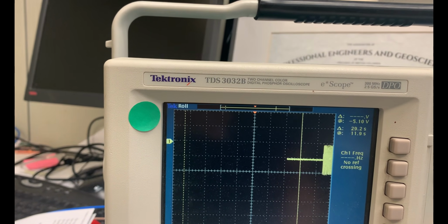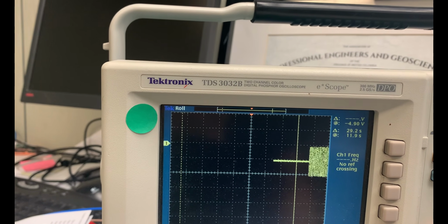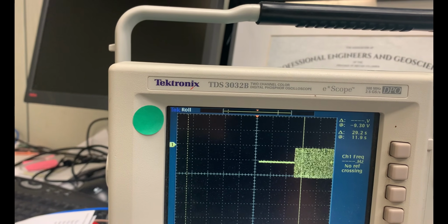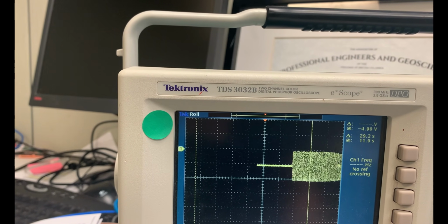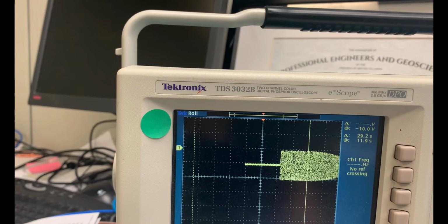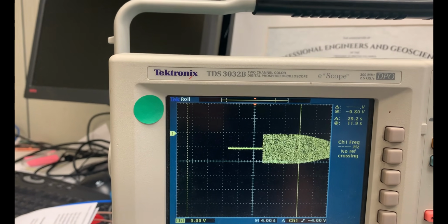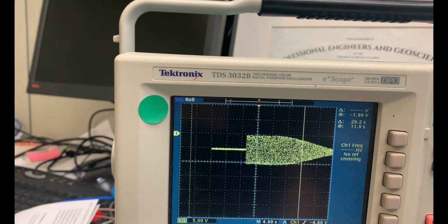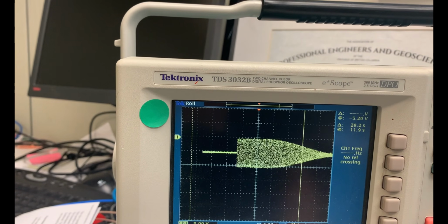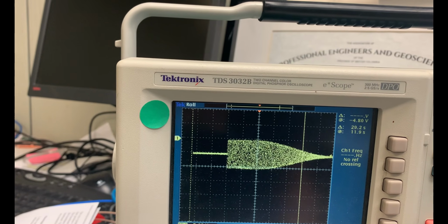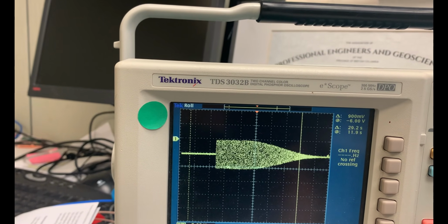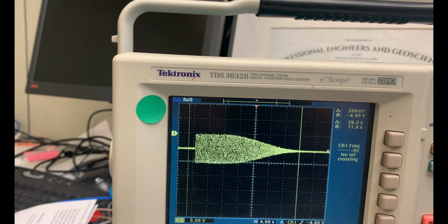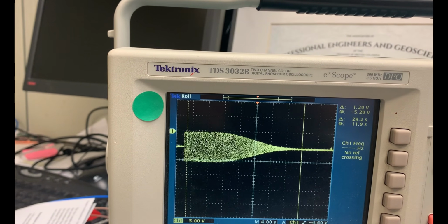Technically, I'm supposed to be looking at two outputs, the I and Q, but because I have only one DAC, I'm looking only at the I component of my FIR filter. Shortly we will move to Vivado. I will walk you through the code, and at the same time we run a live demo on the ILA or ChipScope, and look at both the I and Q waveforms and see how the performance is. So stick around, I will move to Vivado right now.